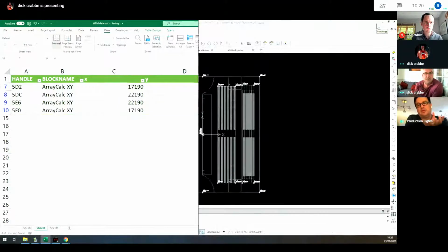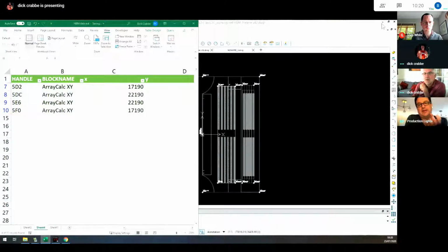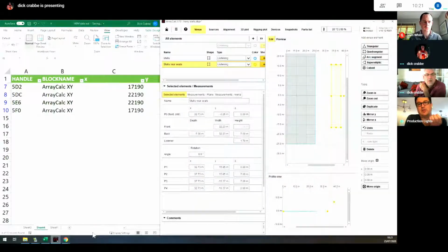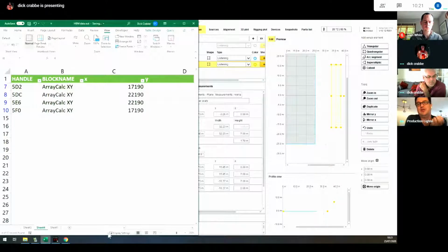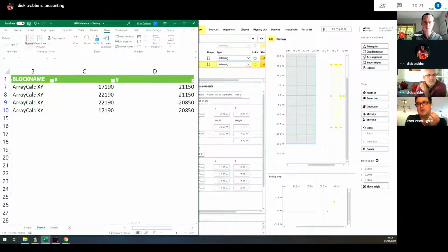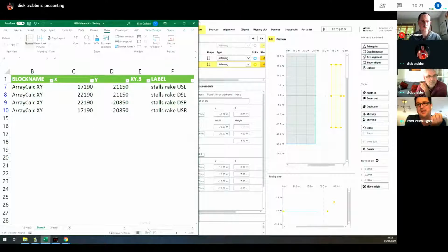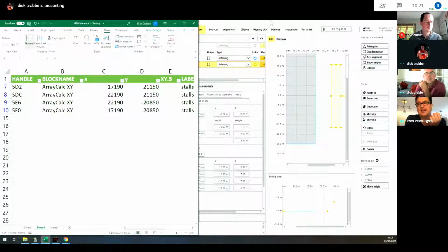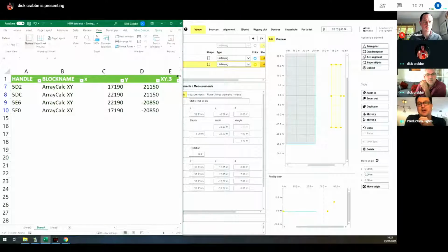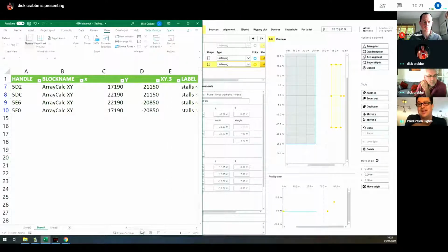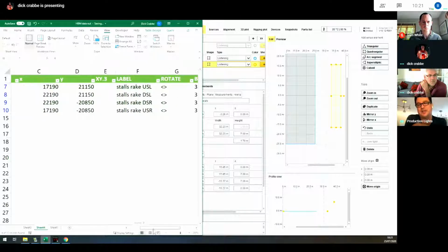Talking everyone through this, one of the ways in Excel, the block has outputted all the data Dick has put in. And this is where Tom and I possibly rewind to a couple of weeks ago, where we talked about how it's really important to put good readable information into your blocks and name your blocks in a way that everyone understands. Because once you've exported this, and in lighting terms we do this, you may have 300 or 400 lights in a rig, and you want to start filtering and understanding it, the information you put into your blocks will help you hugely. And it's wonderful just to see this pull out of Dick's sound, and he knows exactly where that point is, what it's going to be used for.